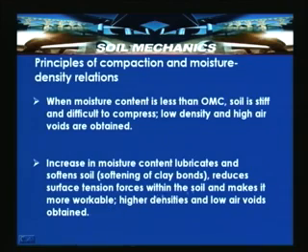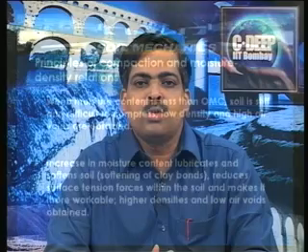So, in the process what will happen is that the particles will take a closest position as possible for a given soil. So, because of this higher densities are achieved and low air voids can be obtained. So, it is not that 100% air voids will be removed, but low air voids will be achieved. So, increase in moisture content lubricates and softens the soil. So, here we should appreciate the role played by the water in compacting the soil.